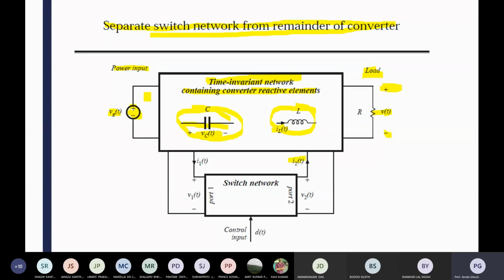If you are not considering those input parameters directly in your calculation, you can say that is the feedback control method. If you consider the input parameters for your calculation, you can say that is feedforward control. I can take one example. In normal convention, voltage mode control and current mode control, both of these control strategies are normally used as feedback control in any control of switching converters.